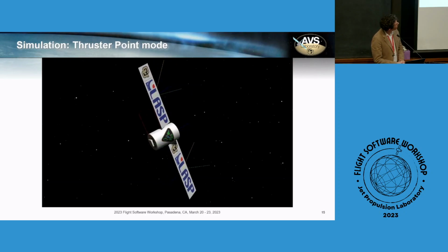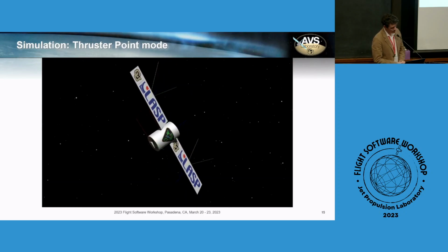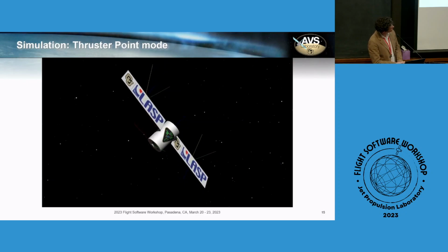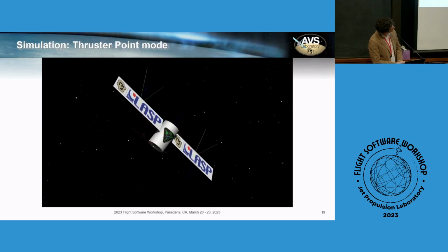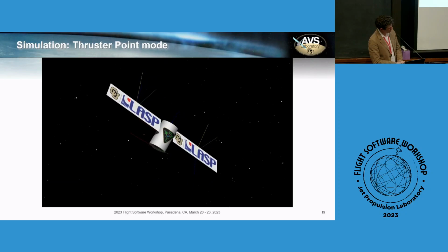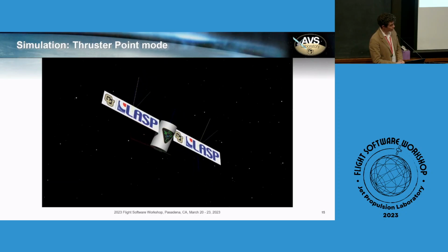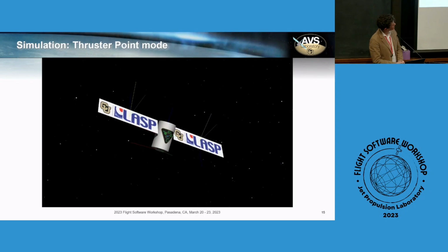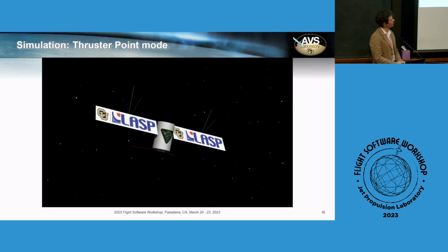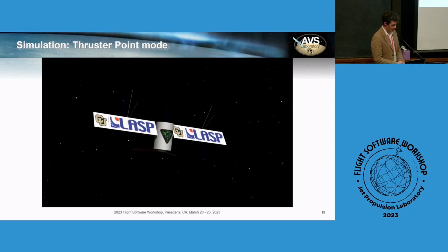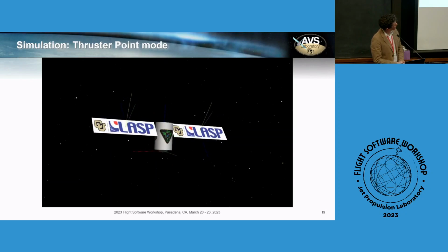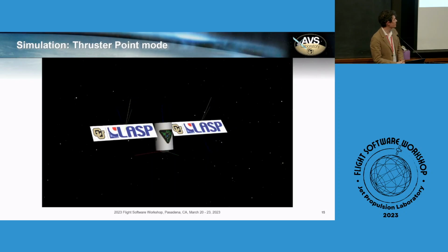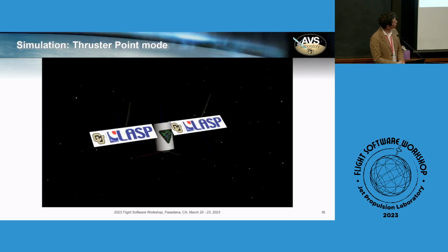It's moving. The platform is that little box at the bottom, so I think it's a little hard to see it move. But if you look at the solar arrays, you can see in yellow the direction of the sun, and in green the surface normal. So you can see that as the spacecraft rotates around, it drags the solar arrays with it. And as the solar arrays also rotate about their own axis, the offset angle between these two vectors goes to 0. So as we are maneuvering, we are achieving the pointing requirements that we want.